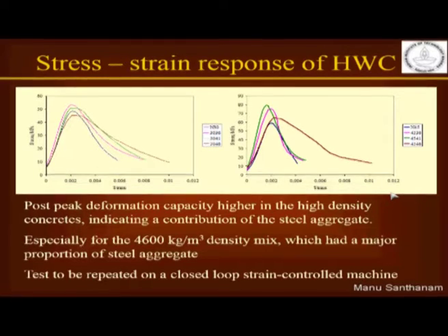Okay. So where do we use high density concrete? We generally use it wherever we need radiation shielding, especially nuclear reactors. Okay. Or when we need some very heavy masses, for example for offshore oil platforms or for dry docks for instance. In those cases we need massive weight, so density is very high.